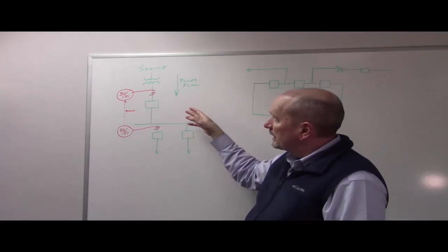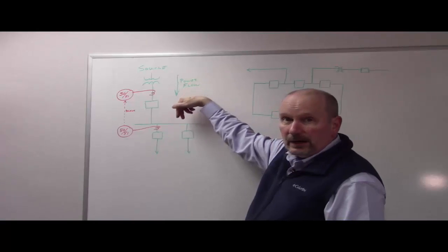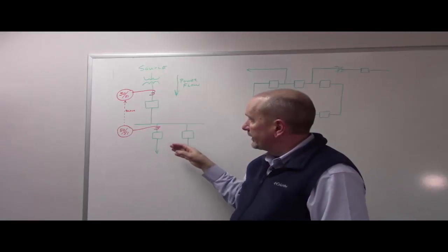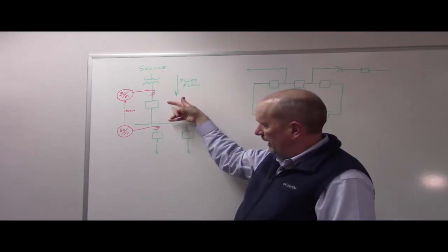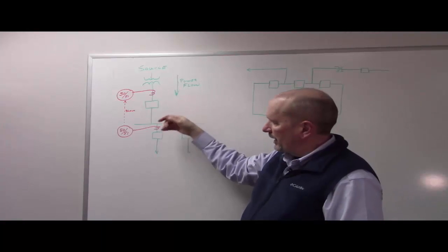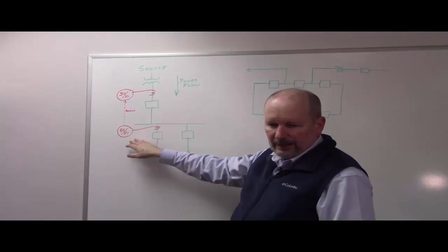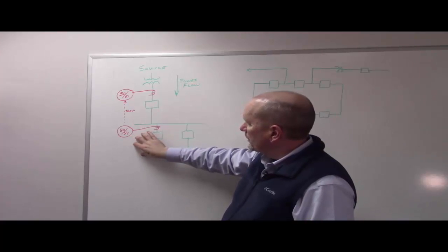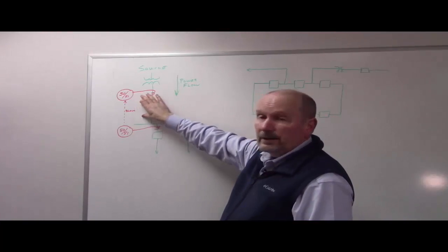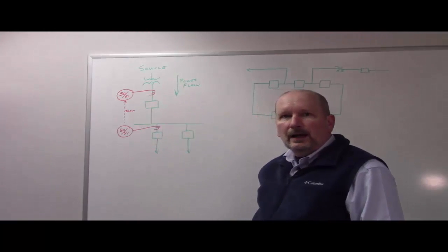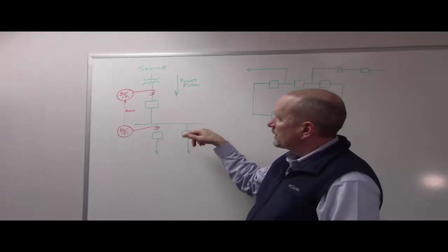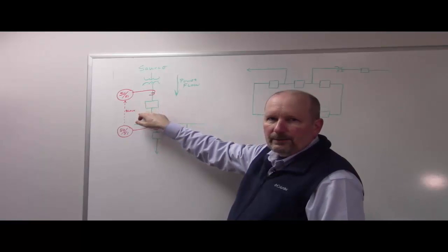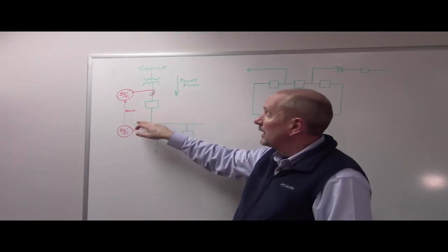Now, typically on these, since power flow can only go one direction, it's not a transmission system. It's actually relatively simple to protect, and you generally do it with coordinated overcurrent relays. You have 50-51s, which are inverse time and instantaneous overcurrent settings, and you just set the feeder breaker to trip a little bit faster than the main breaker. Pretty simple, and in some cases there have actually been schemes to speed this process up, where instead of allowing a 5 to 10 cycle lag between the two, you just allow like a 2 or 3 cycle lag.